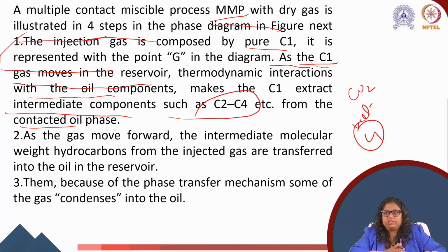As the C1 is injected, it moves through the reservoir and contacts the oil, and it extracts these intermediate components from the oil phase.